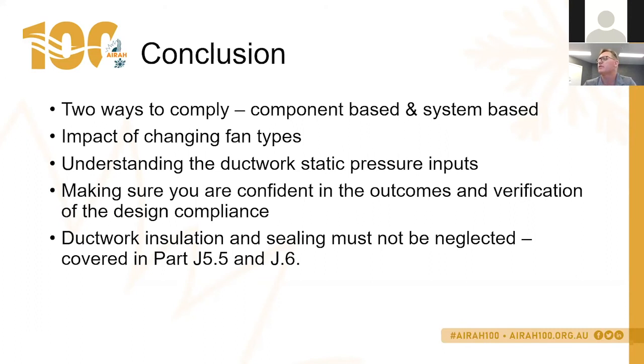When calculating the pressure drop in a system, we normally allow for dirty filter pressure drop. Yes, we normally do. The calculator has an allowance based on a clean filter. So you will get a significant difference between your specified static pressure loss and the calculator, which is based on clean filters.